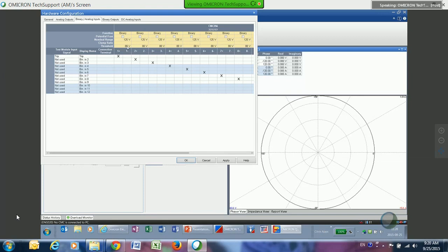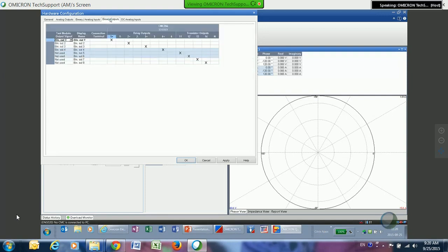And what this does is set up your nominal value, and then down below you see this threshold value, and that is 70% of your nominal range. What that means is anything above 88 volts in this case is going to register as asserted, or basically a binary input is going to be active at that point in time.